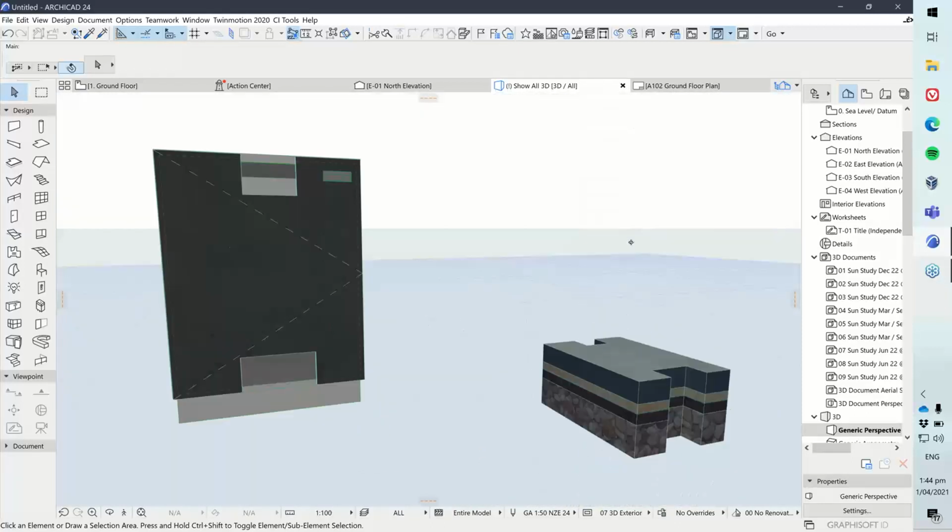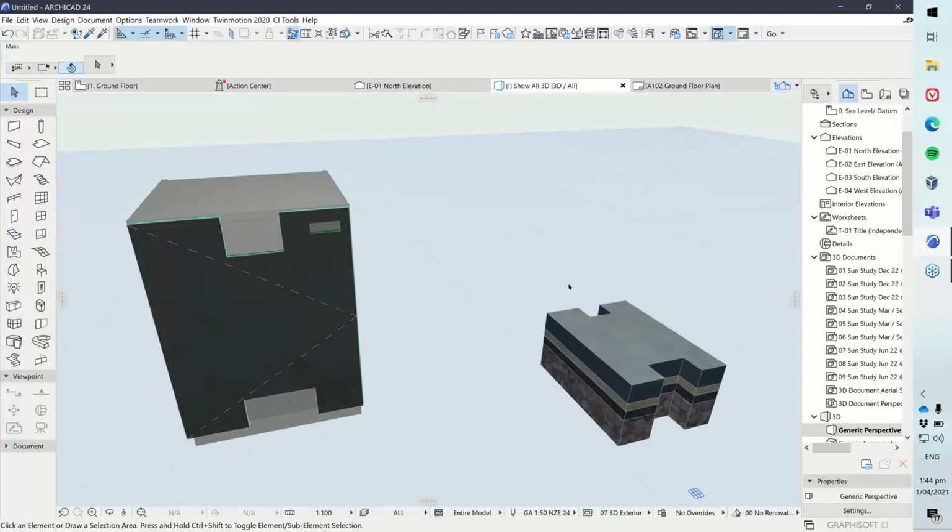It's a little bit hard to tell on this one because there's not much to do, but it will essentially squish the shape to fit the size of your cabinet door. So if you do this and find that it gets messed up in terms of the proportion of the shape that you drew, it's most likely just because the shape that you drew was in a different proportion than the cabinet itself is set to. So you need to either draw your door front in the ratio that you want your actual door to be, or just modify the size of your cabinet so that it fits what you want there.